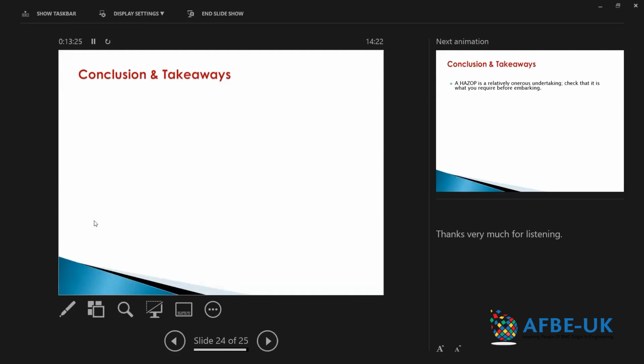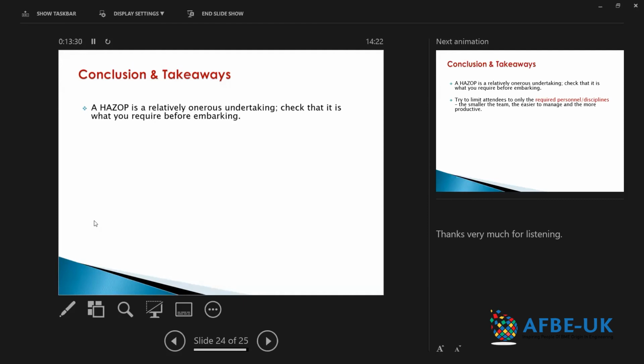Right. I'll just wrap up now, and we can go to the questions. So we've said that a HAZOP is a relatively onerous undertaking. Check that it's what you require before you actually start. And that's where the HAZOP decision matrix and other triggers for a HAZOP come in.